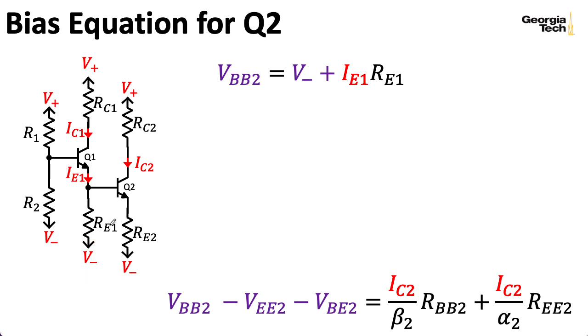All right, so by superposition, let me first focus on V minus. If I'm focusing on V minus, then I open up this current source here. And so there's no current flowing here because computing a Thevenin equivalent, I cut the line here. So there's no voltage lost. And my influence on the Thevenin equivalent voltage is just V minus.